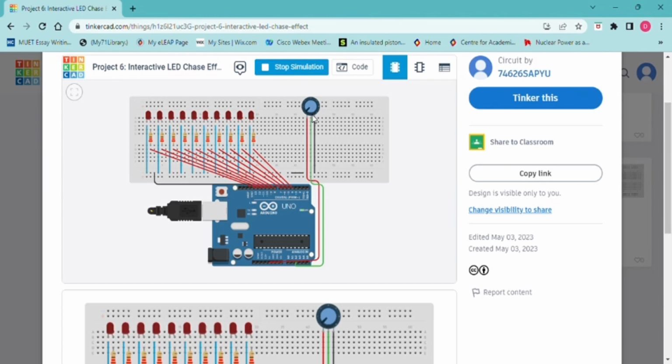By adjusting the knob, a voltage between 0 and 5 volt will be leaked from the center pin, and we can read the value of the voltage on analog pin 2 and use its value to change the delay rate of the light effect. Now the potentiometer can be very useful in providing a means of adjusting a value from 0 to a set amount. An example is the volume of a radio or the brightness of a lamp. In fact, dimmer switches for your home lamps are a kind of potentiometer.